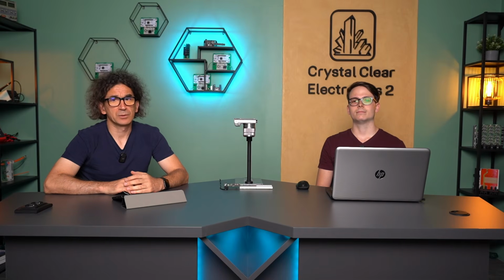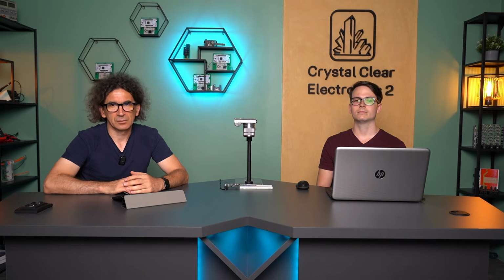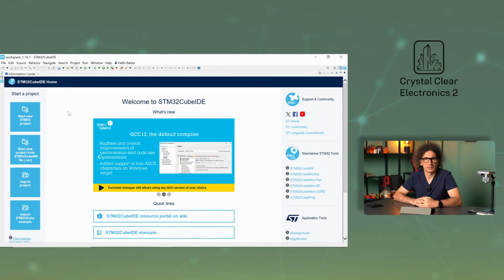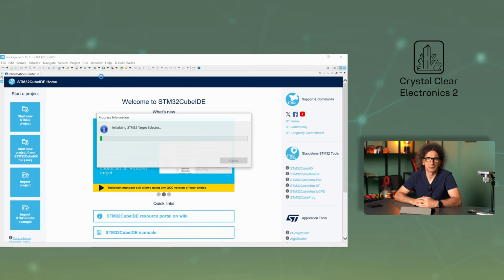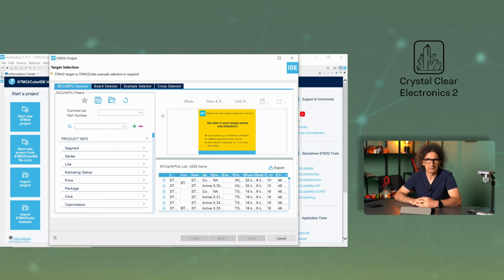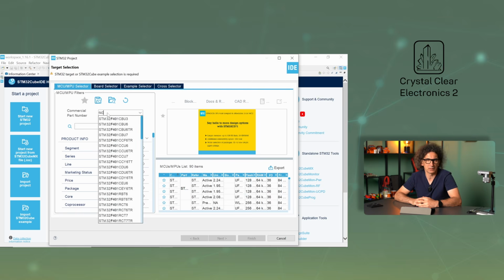Before we delve into the ins and outs of coding, we need to prepare the scene. Our development environment is still STM32 IDE, so let's get started. Create a new project. File/New/STM32 Project. Select the F405 VGTX microcontroller, as we have already done, and make the necessary settings.